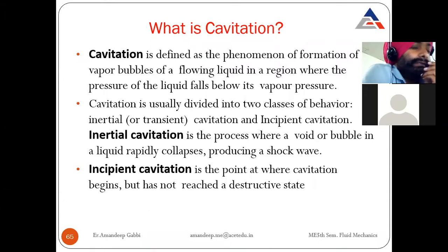At that particular point there is a formation of bubbles. The bubbles start moving ahead, and after that they collapse. When they collapse, sound is produced, and this process of formation, movement and collapsing of bubbles is called cavitation. Now let us discuss it in detail.